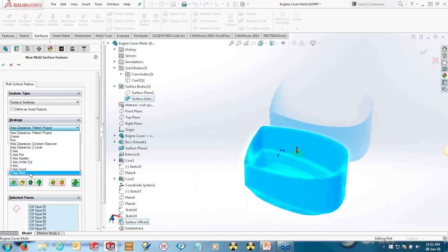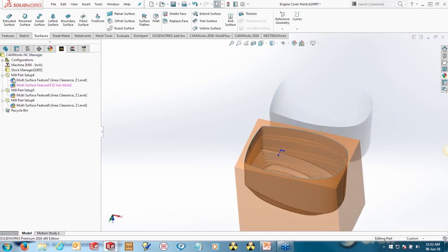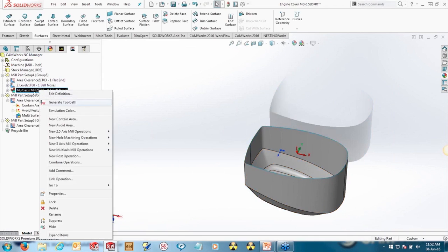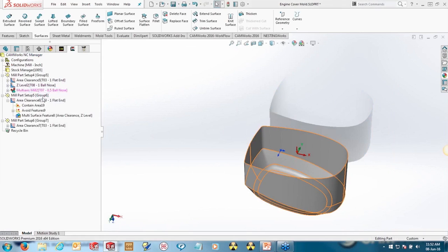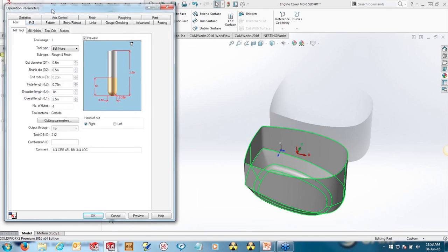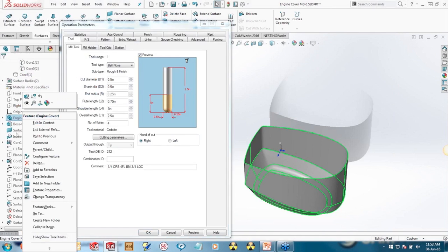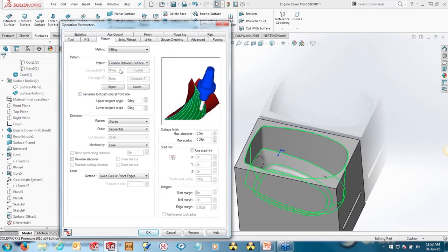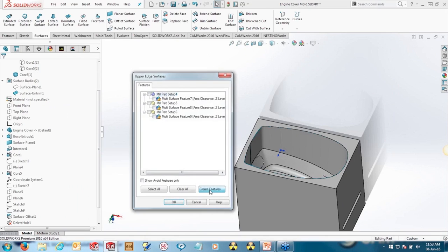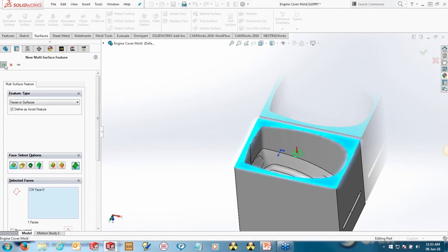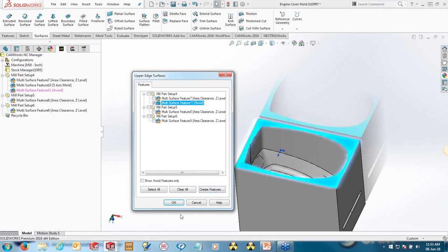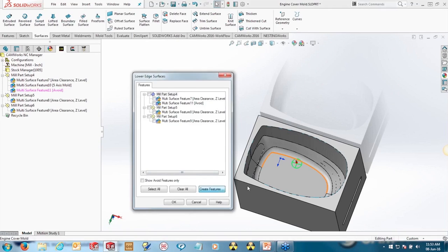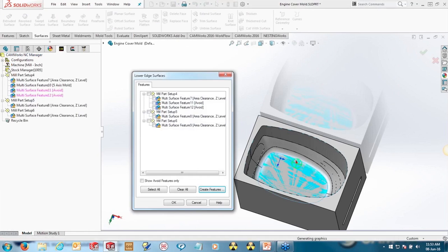And in this case, I've got a 5-axis mold strategy that I've created here that I've just saved out. I can use that to go in and grab all the tools. The only thing I would need to do is maybe go and select some of the pattern geometry. Let's just bring back the main tool there. In this case, I'm using a flow line, and I'm going to grab the upper surface over here to drive it towards the bottom. So we'll use this one for the upper, and then I'm just going to go and grab another one, this one, to drive it to the bottom of the geometry.